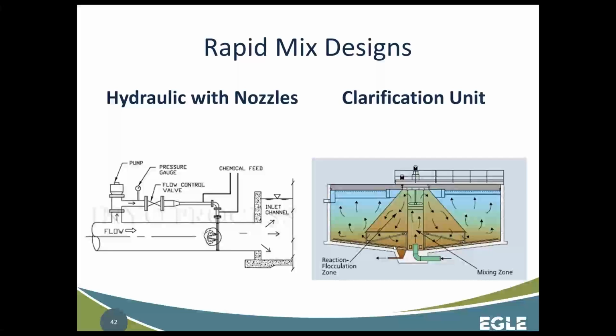And you can kind of see down here, they're depicting these arms. This is going to be scraping up all the solids that are accumulating in the bottom of the clarifier, getting them into this sump. And then this can be commonly referred to as a sludge blowdown. So there will be a valve somewhere here. They can open up that valve and the hydraulic head will push that sludge out of the sump. So pretty common. I guess one thing, these are susceptible to thermal upsets sometimes. So if you have a drastic change in water temperature, that can be an issue for these.